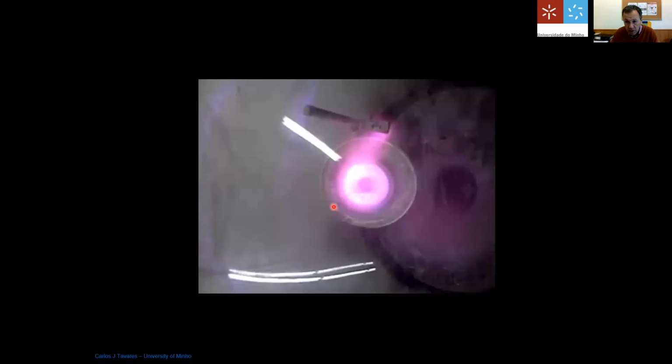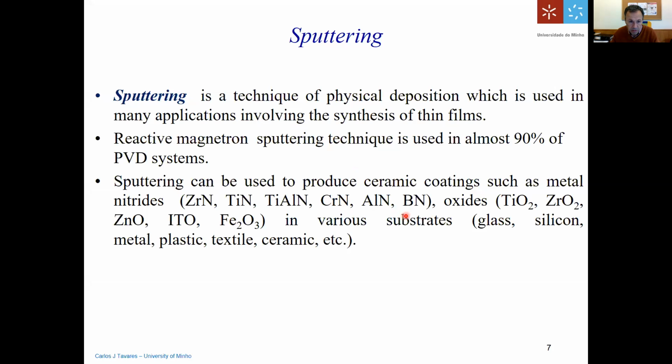You introduce nitrogen, okay? If you want to make, for example, titanium carbide, then there is no gas solely comprised of carbon atoms. You have to introduce a gas which has carbon, for example, methane or acetylene, or CO2. You can introduce this gas, and the carbon will be used to make the bond with the metal, of course, and to make this titanium carbide coating, for example, okay?